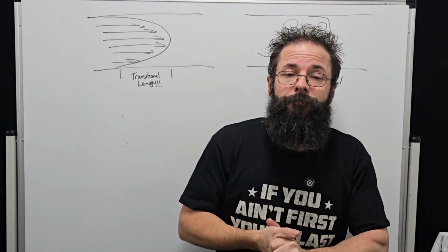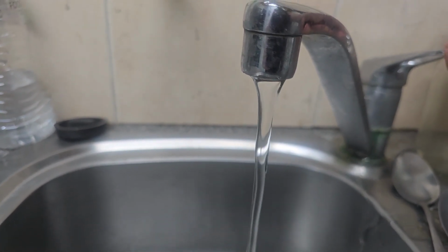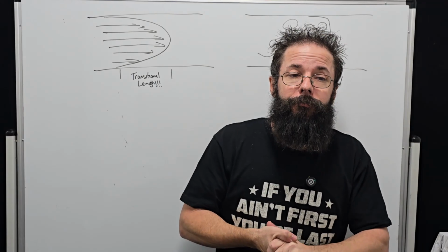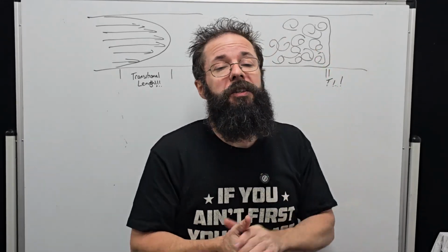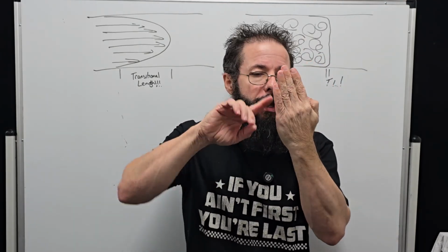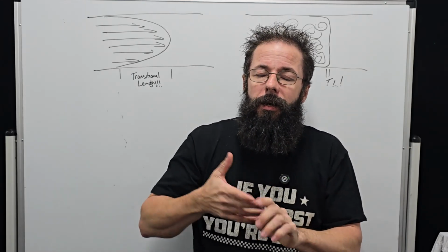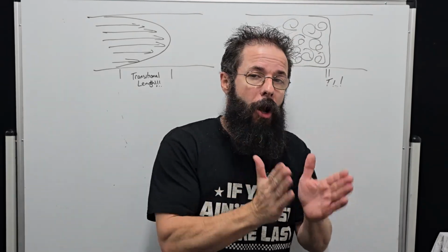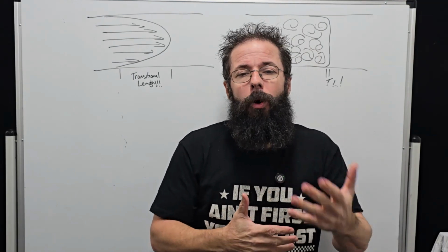If we look at this water here, laminar flow, directional turbulent, laminar, turbulent, laminar, turbulent. Straight away, you can see the difference between laminar and turbulent. It's not doing the textbook big eddies. We won't see that unless we have a wall in the way, and then we get an eddy wrapped around the back of an object. And you can see in the water, one is low velocity, laminar, and then one is high velocity, high inertia, turbulent. And it's directional turbulence, and that's what we're using.